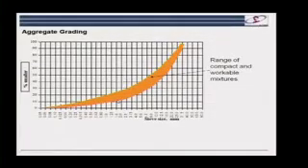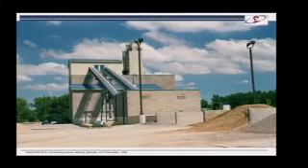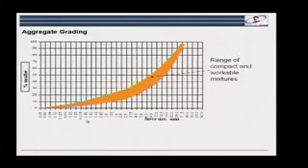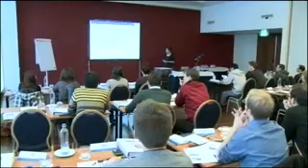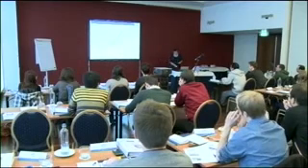And on the basis of experience, we know that we want to have material in this region, and there are very simple ways we can reconstitute all our different fractions of aggregates to give us a total grading in this range. And those blue lines, these are just various curve-fitting exercises that people have made to give a kind of mathematical description of that orange zone. But it's important to realize that orange zone is really just the basis of a long knowledge and experiments over the years of what gives the best mixture.